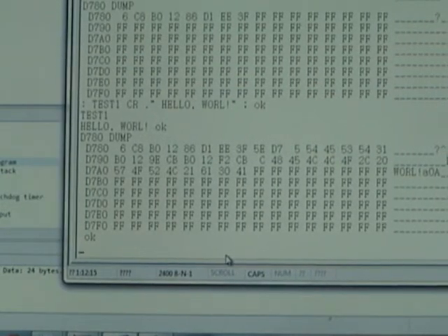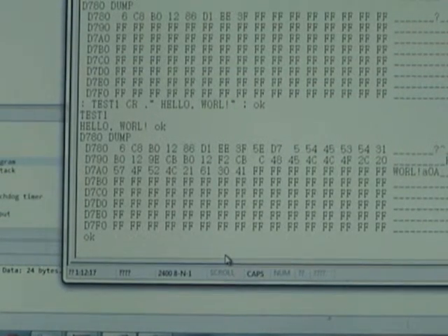But when you add new code, it is very difficult to forget because you cannot always go back to the 512 byte boundaries. And so I would suggest that you don't erase anything. Just keep on adding new words until you fill the whole memory.